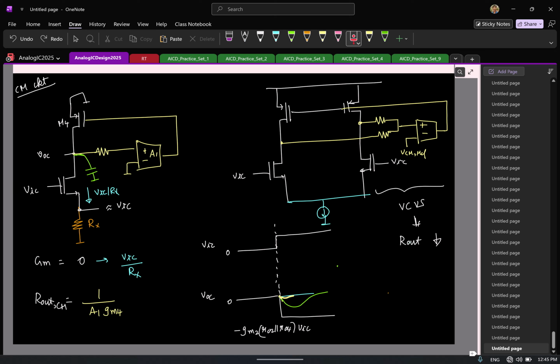So that is why it's preferred to have both of these at the same time. And as I already mentioned, it is very important to have this common mode rejection, at least for the first stage. If you have multiple stages, the stage processing the input signals, Vi plus and Vi minus, must definitely have a tail current source to give common mode rejection. Okay. Any questions?